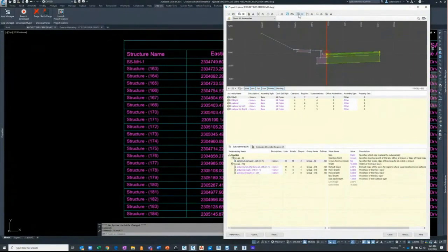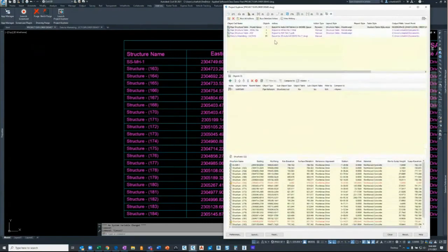All right. His second question is, when you edited your structure table, you turned off the general pipe network table above the structure table. Where did you go to do that again? Okay, so if I'm in my data sets over here, and let's look at that first one that I created, my structure table.